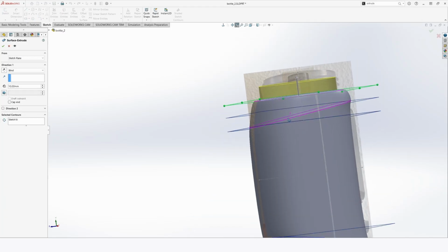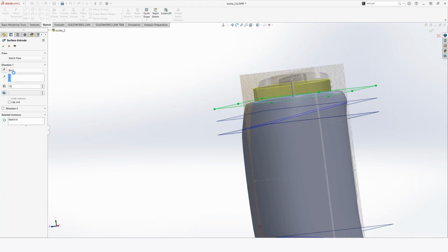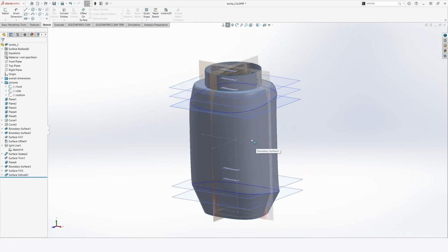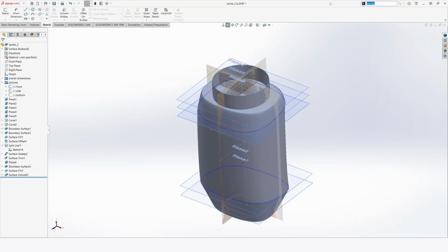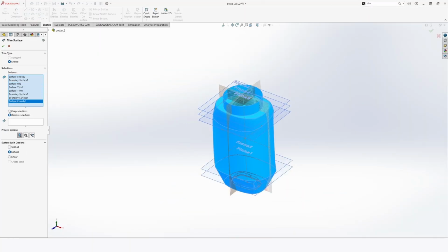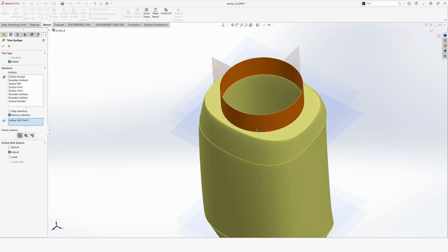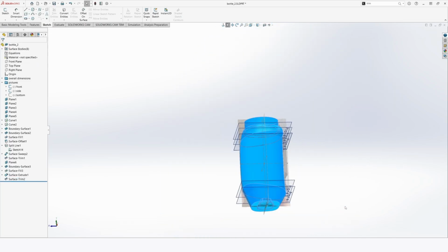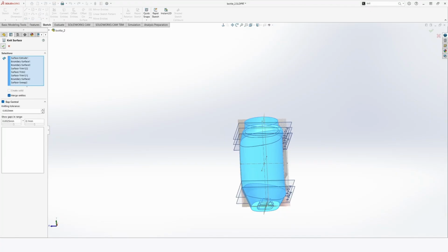See what that looks like on the side view. We could definitely go a bit higher. All right. Yep, that's looking pretty good. I'm going to do a trim where I remove this surface, and looks like everything else can stay. And we want to knit these surfaces together so that we can do things like fillets down the line. Merge entities.